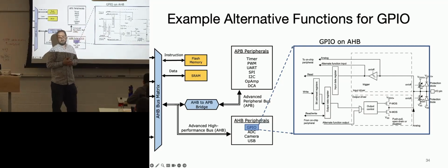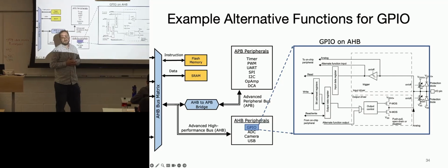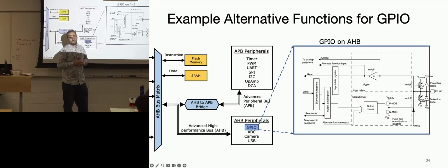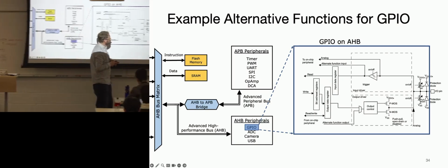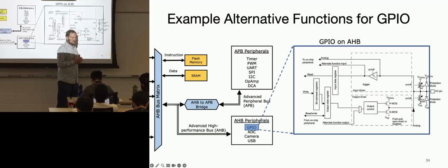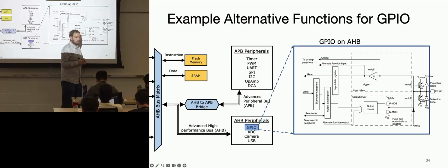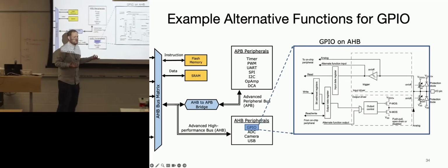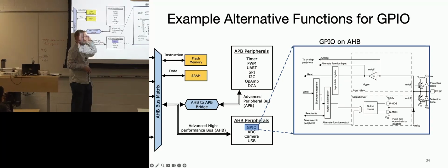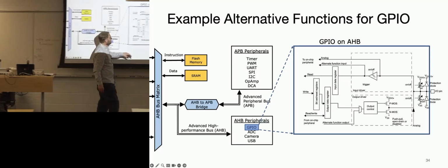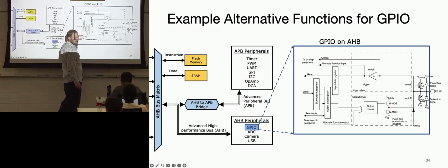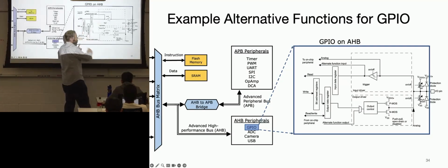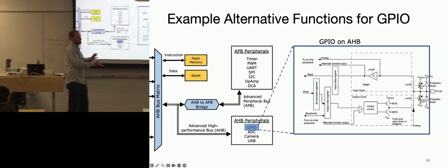What questions do we have about GPIO pins? Zero questions. I just have a question, so for the pull up, pull down, when you're controlling those, is the address of those stored somewhere in memory as well? Yeah, there's a control register for it. Gotcha, so inside of that thing, there's a register that says whether it's. Yeah, it's not shown here, it's shown in the data sheet, but there's another little register here, and we didn't show every single line that goes over here. So the only way you can control things is basically through a register.